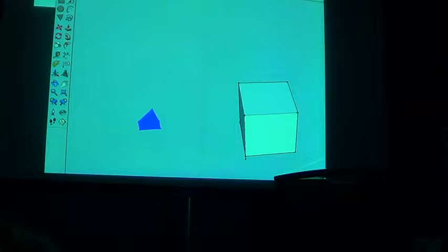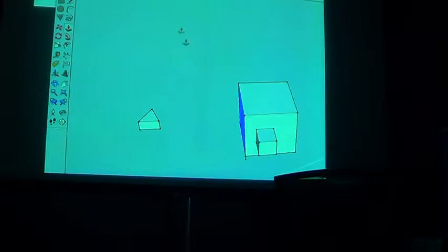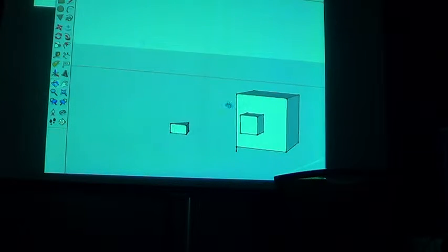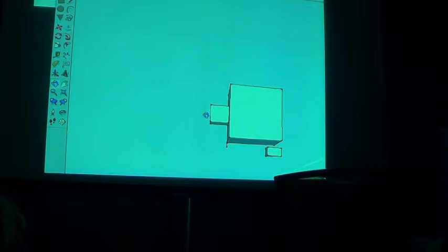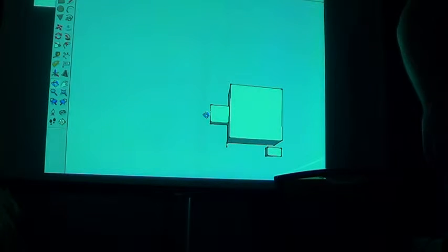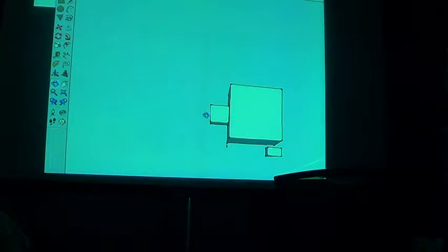Little things that don't do well with 3D printing are overhangs, at least with most consumer level printers. If I were to create a smaller box right here and pull that out like this, that overhanging box wouldn't work. The printer works by essentially melting plastic on previous layers. If it's not a very steep angle, less than 45 degrees, it can kind of build a little bit on itself. But at a 90-degree angle, the first 10 layers on this part are just going to fall straight down. There's nothing for them to be supported by.